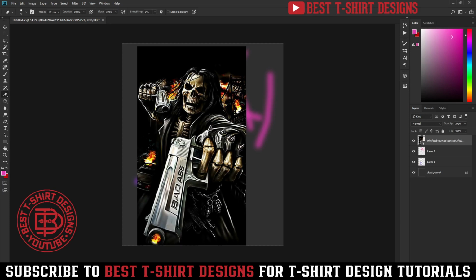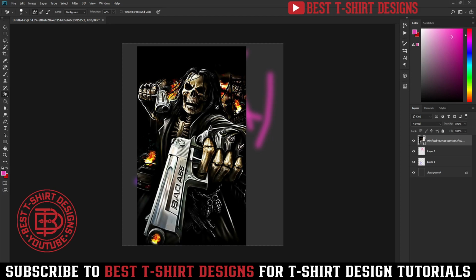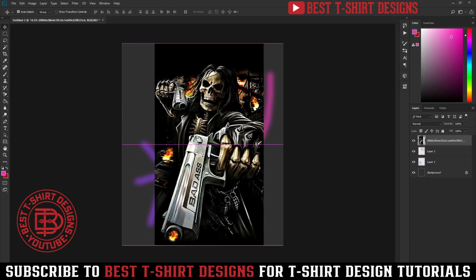If I select my eraser tool, it is showing me this cross icon here, which means it is not going to work. That is because we brought this image in as Place Linked. To fix that, we have to right click on this layer and click on Rasterize Layer. That will unlink this image, which means it is no longer linked with anything from my computer. This is just a simple image in Photoshop. Now if I select my eraser tool, I can erase part of it.